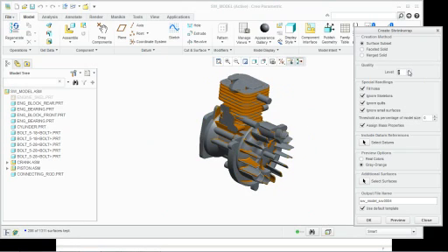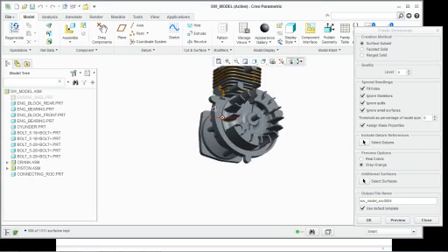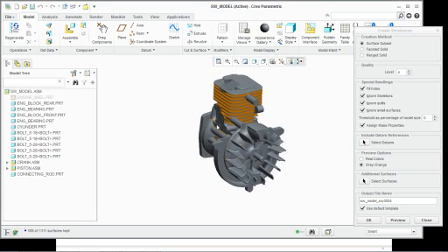Click OK. That's just an alert saying, you know, hey, you're going to change some stuff here. Now if I click Preview again, notice that a lot of those orange surfaces have gone away. I still have some. Still going to exclude a lot of these, but my geometry is a little more accurate to what I want it to be. As you notice down here at the bottom left, 588 of 1,311 surfaces have been kept. If I change that level, let's say we'll change it all the way up to 8 and click Preview.